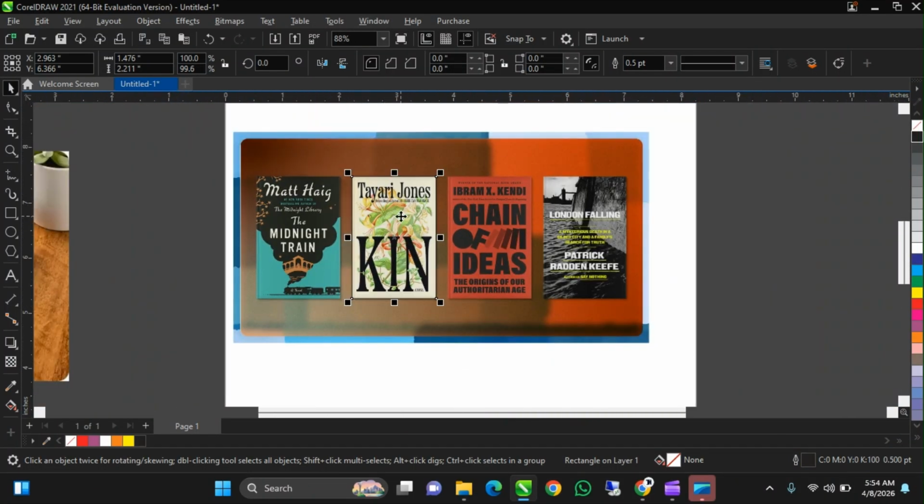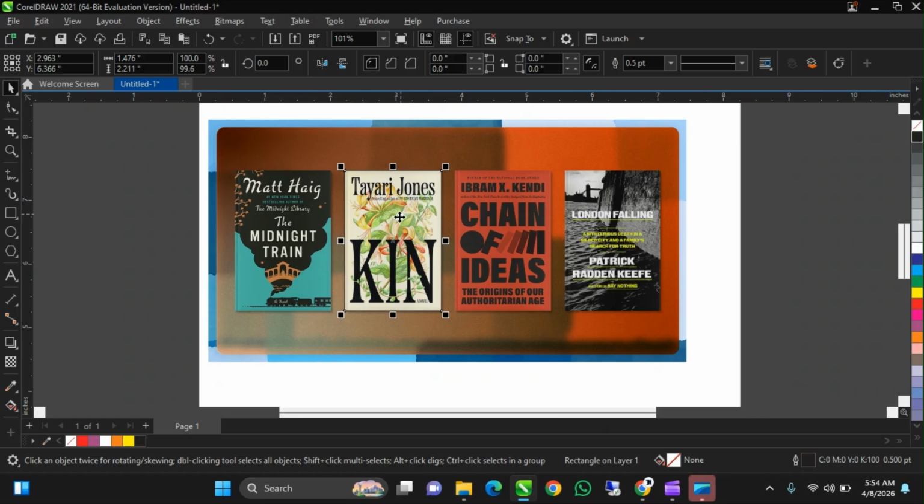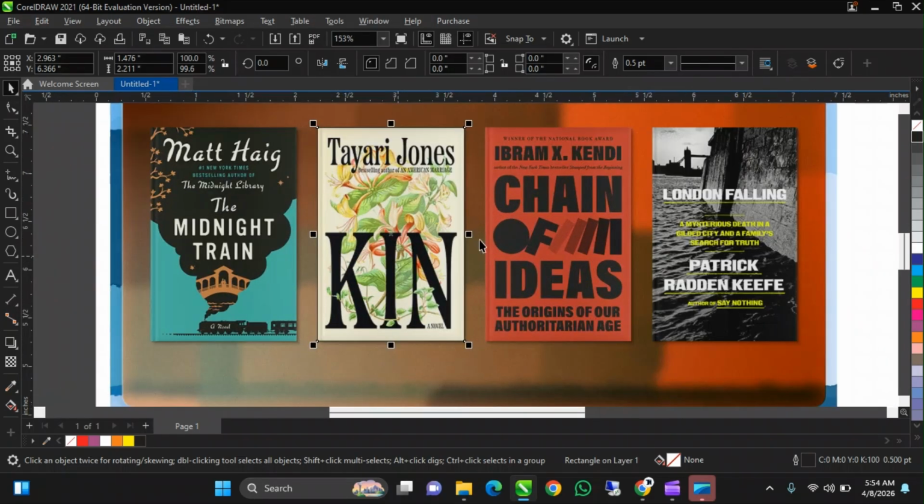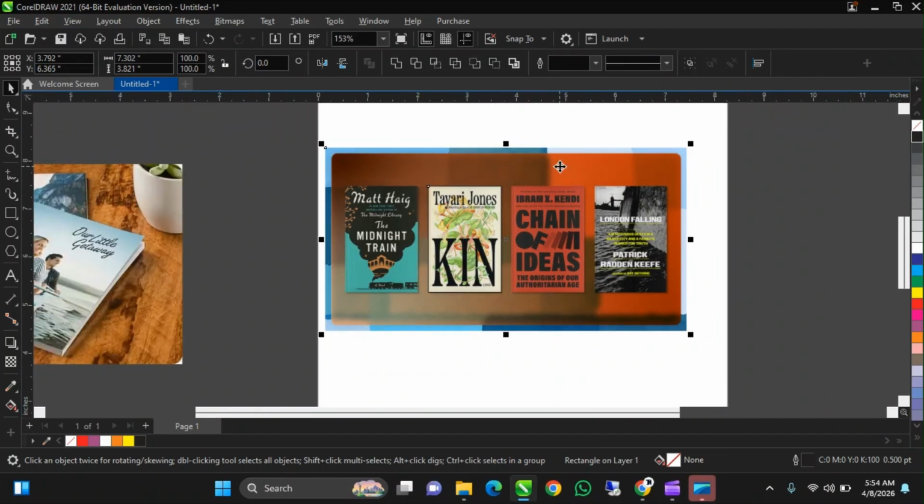The same process: select the rectangle, it's already selected. Then hold down your Shift key and select the image totally. You have two objects selected. Remember, you first select the rectangle. Don't select the image first. It comes in an orderly pattern. Select the rectangle first, hold down the Shift key and select the image. And remember the Intersect tool here.